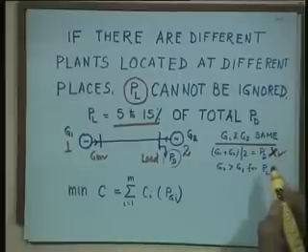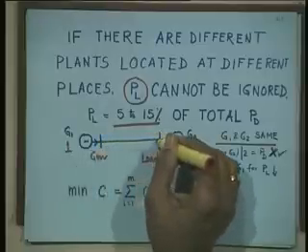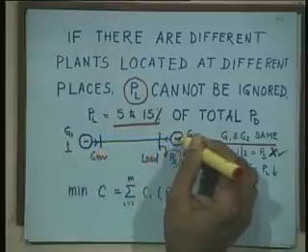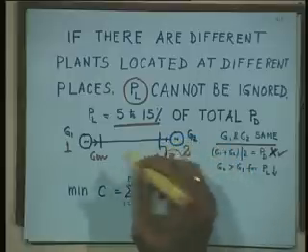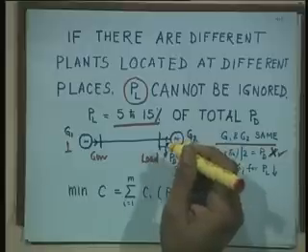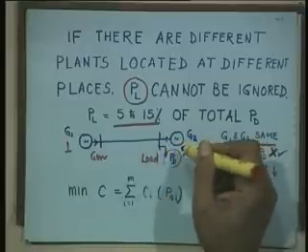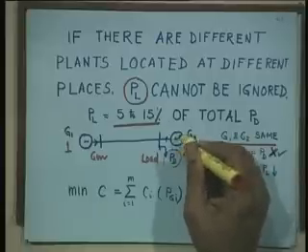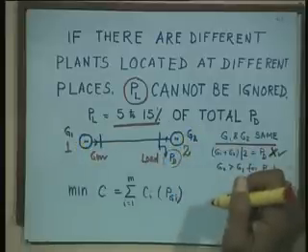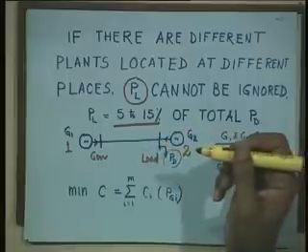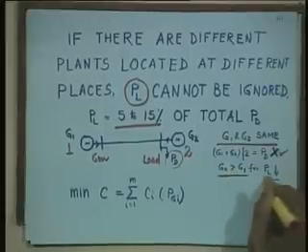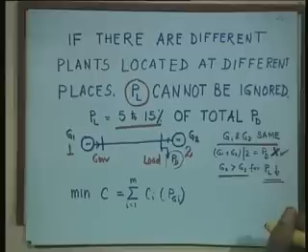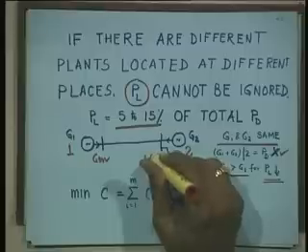Why is it a wrong solution? This generator has to travel all the way to supply this load, whereas this generator is right close to the load. So, even a normal IQ, I am not talking about high IQ people, normal IQ people or low IQ people will understand it will be wise, it will be prudent to supply more power from G2 rather than G1, because G2 transmission loss is 0, it is right there, and hence G2 should be more than G1 for less losses, and hence that earlier criterion cannot be applied when losses are to be considered.